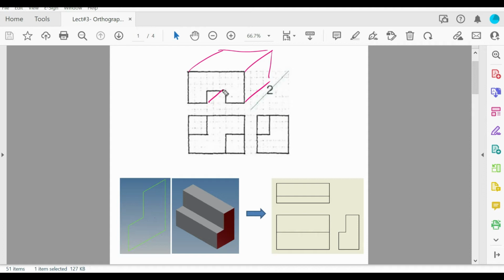In general, it depends on the multi-views you have and how complex the multi-views or the part are. So sometimes you need more than extrude, sometimes you need forming. It depends. Now let me start and try to find the proper 3D representation of the multi-views I have. By the way, this is the miter line. I will use this miter line to transfer dimensions from one view to another view.